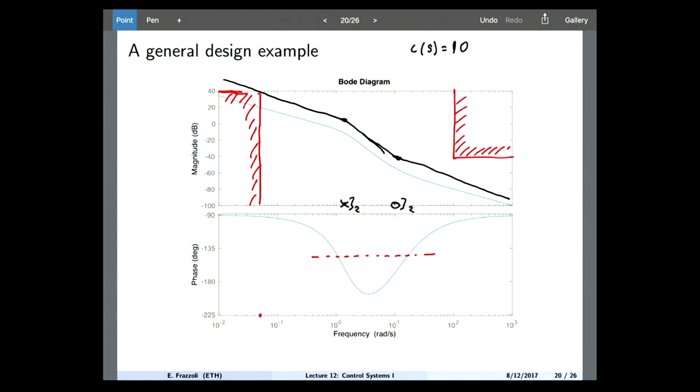Yeah, we could use a lead compensator. How would you choose this lead compensator? The square root of A times B needs to be 60. So both the pole and the zero, we use the square root of those. And we need to shift up the phase by 40.